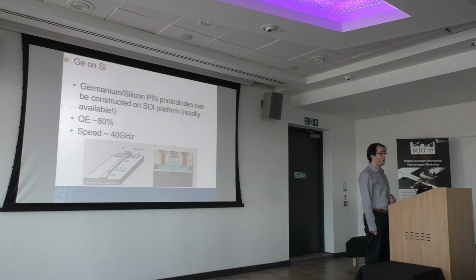They're very, very small, which actually turns out to be a large advantage for photodiodes. One is that their speed is quite fast, so without too much work, you can get up to 40 gigahertz. The quantum efficiency with the photodiodes that we work with is limited to about 80%. This is not intrinsic to the photodiodes.